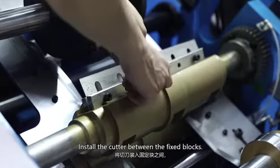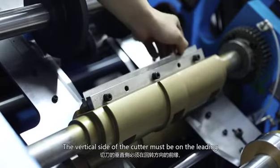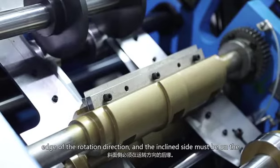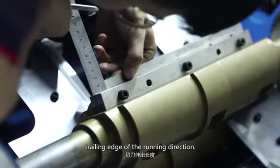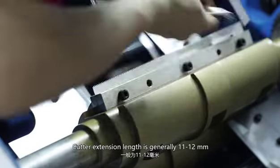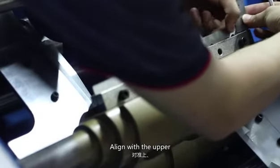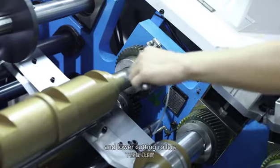Install the cutter between the fixed blocks. The vertical side of the cutter must be on the leading edge of the rotation direction, and the inclined side must be on the trailing edge of the running direction. Cutter extension length is generally 11 to 12 mm. Lock the screws of the fixing block. Align with the upper and lower cutting rollers.